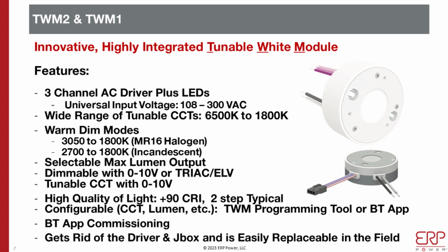Both TWMs are very innovative designs, and they are highly integrated light engines. TWM comes from Tunable White Module. Think of it as having a 3-channel AC driver built into the light engine. So it's AC input, universal voltage, 108 volt to 300 volt AC.